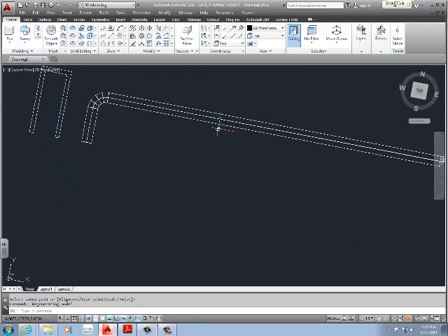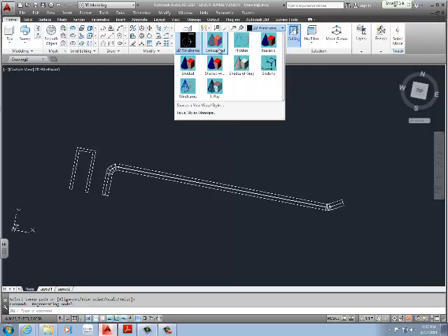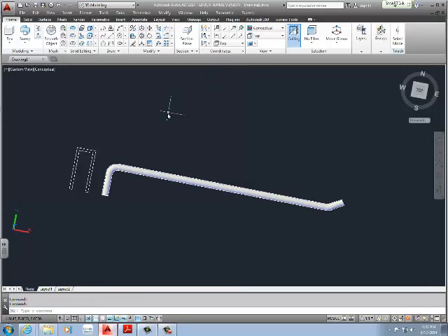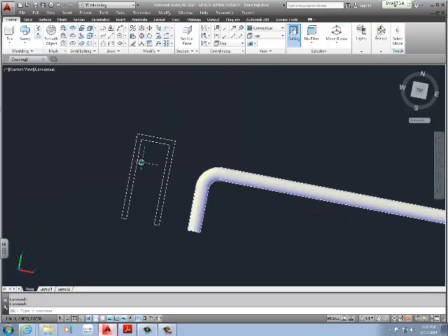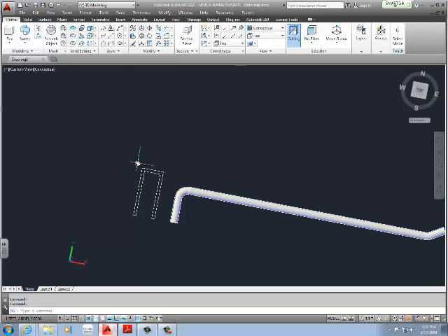If you want a better visual view of your 2D wire, you go into your view tab here, and you go to conceptual. For this rectangle, we're not going to work on creating it as a polyline, even though it would benefit us a little bit, but we're going to use the easy command of press pull.